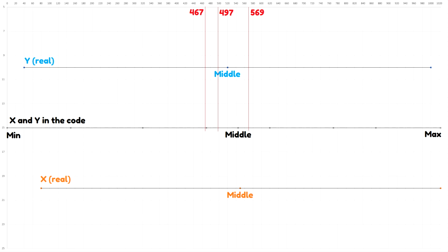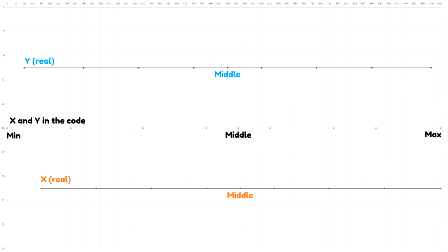The issue appeared when the joystick was at the bottom stop in the x-axis. The other axis starts to move a little. When the x-axis was in the bottom stop position, the y value was 467. But you can see this value is just a little bit outside the dead zone, so the y-axis was moving a little. So here what I did, I redefined the middles, and I redefined the dead zone to be a little bit larger to encompass the defective values.